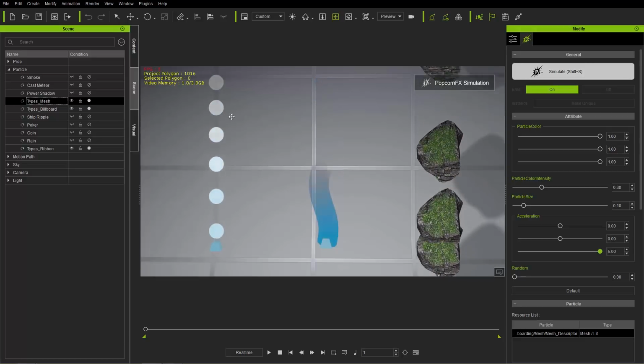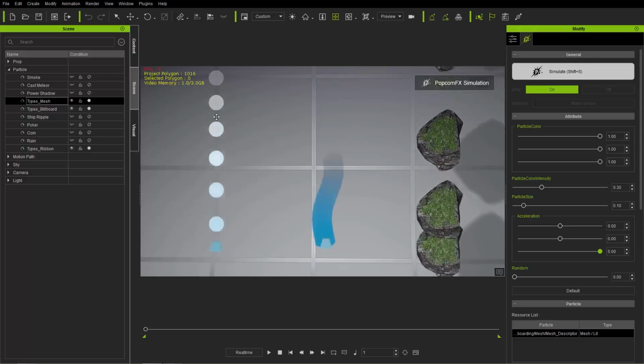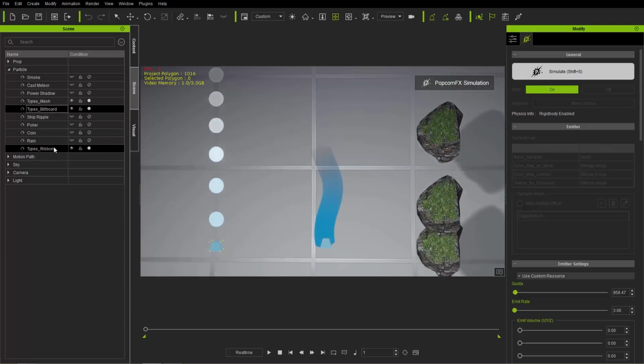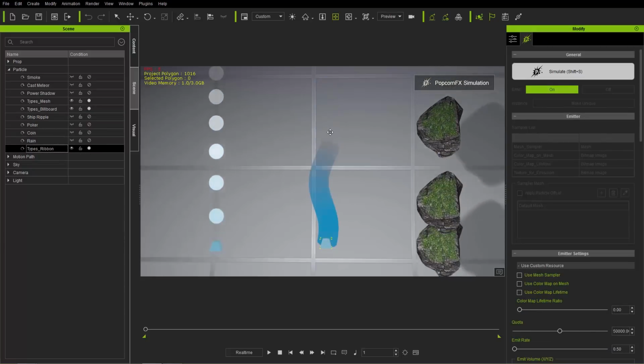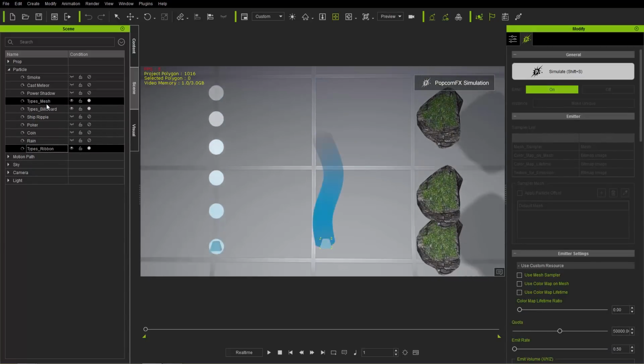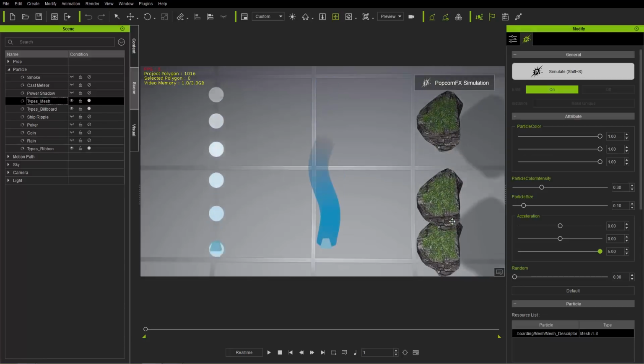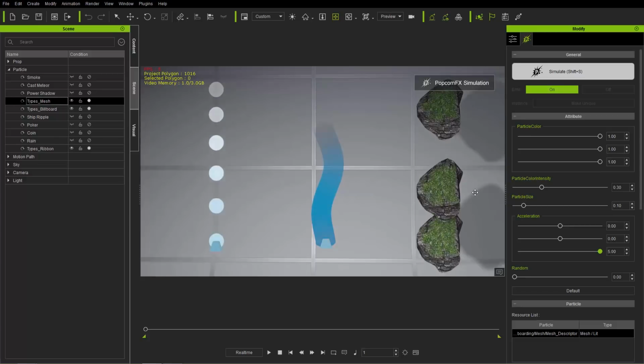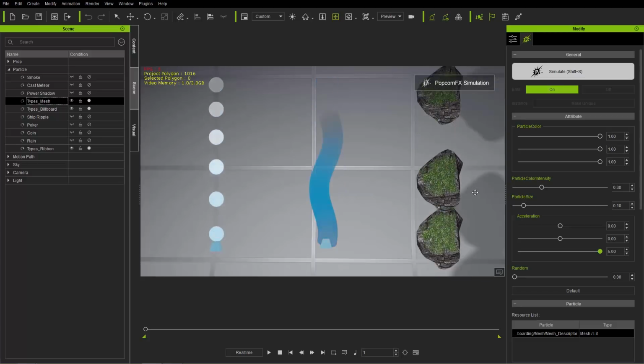And you can see on the left here we have our Billboard, just a bunch of different dots shooting up in a repetitive pattern. That's the Billboard type right here. Okay, and the middle one is the ribbon type. We're going to be talking about that as well later on. And on the right we have the mesh type. So this is actually emitting its actual meshes. You can see it's casting a shadow. So we're actually emitting different meshes that have their own geometry with this particular emitter.